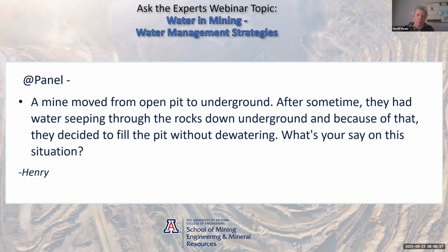If you put any kind of tailings above the open pit, it's going to build up water, so you have to really monitor the subsidence and make sure you're not going to create a situation where you get a sudden rush of tailings into the underground. Yeah, the key is understanding what the relationship is between the open pit and the underground mine before you do any of that anyway.